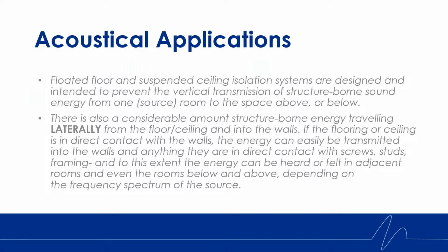But if it is, you get that structure-borne energy into that wall, and that re-radiates out as airborne sound, so it becomes audible. And depending on the frequency spectrum of the source and really the guts of the building and what's connected to what, it can be audible in the rooms above and below.